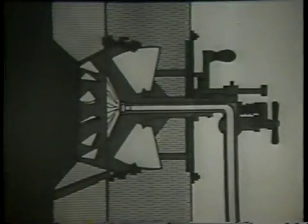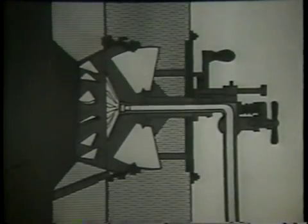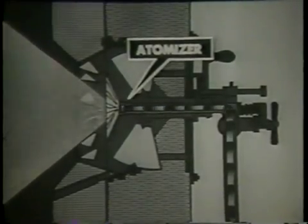As you have seen, the burners in a boiler provide the combustible mixture of air and fuel oil that is burned in the boiler furnace. As seen in this view of a typical burner mounted in a furnace wall, the burner's atomizer reduces the fuel oil to finely divided mist-like particles. That is, atomizes the fuel oil.